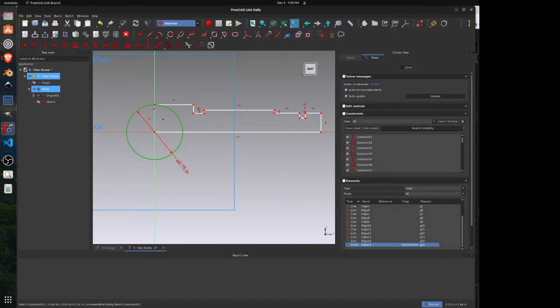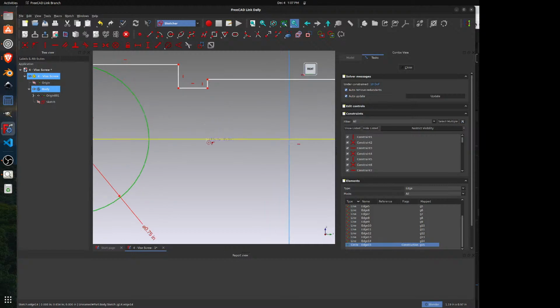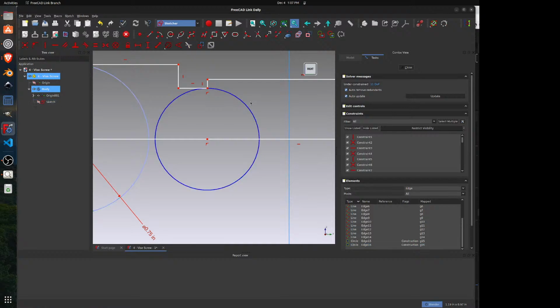And that way I know that this line is going to end up being a 3/4 inch diameter in the end, a 3/8 radius automatically, because the circle's center is at the axis of rotation, and it's coincident with the line for that diameter. I could come in here and do the same thing for this diameter, which I'm pretty sure is a 1/2 inch. So I want to come in here and draw a circle from there to there, select it first, make it construction.